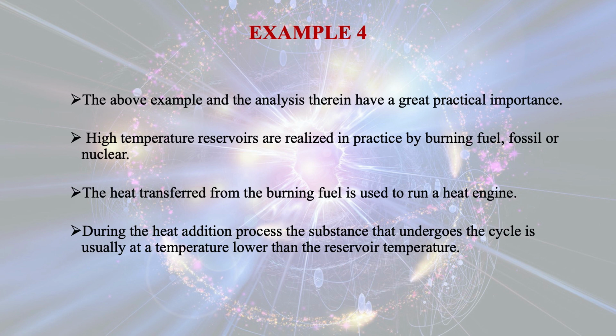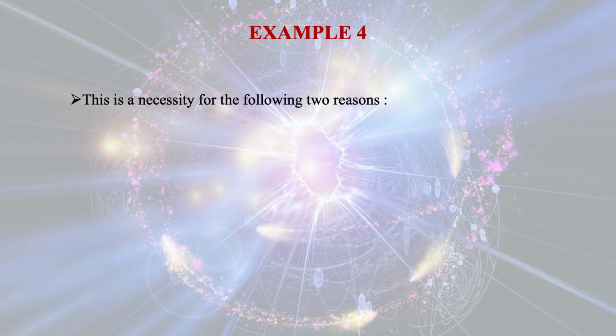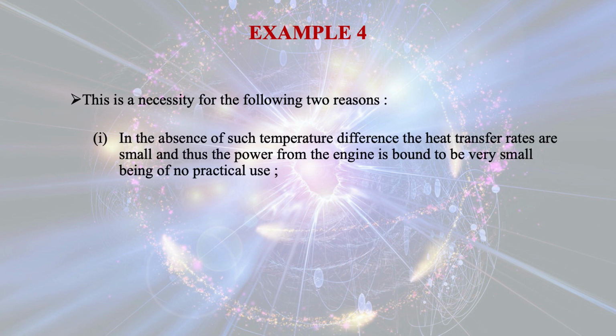During the heat addition process, the substance that undergoes the cycle is usually at a temperature lower than the reservoir temperature. This is a necessity for two reasons. Number one, in the absence of such a temperature difference, the heat transfer rates are small and thus the power from the engine is bound to be very small, being of no practical use.